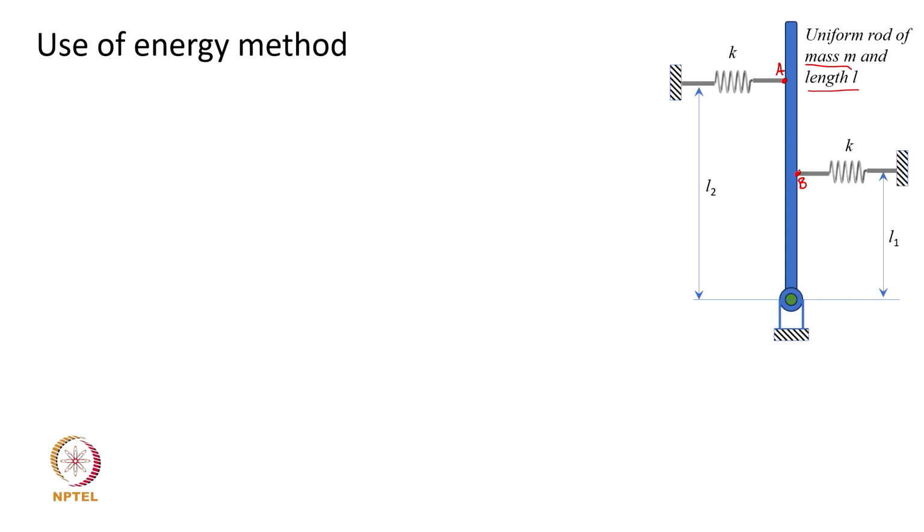Although we are going to implement the energy method to explore the governing equation of motion and the subsequent expression for the natural frequency, just for the sake of comparison, I would like to quickly analyze this problem using the conventional application of Newton's second law. So, we all know that it would pertain to getting the forces located on this bar as a free body. The moment this bar moves about the fulcrum here at the base, the hinge about which the bar is expected to rock.